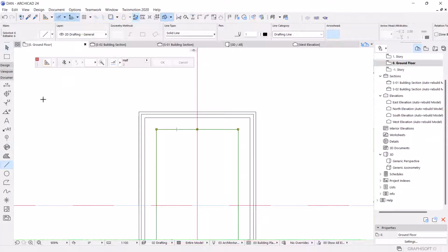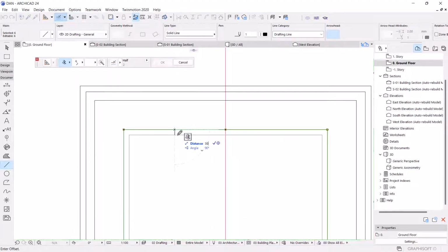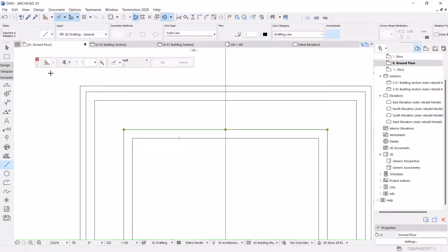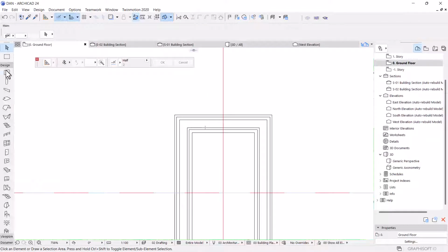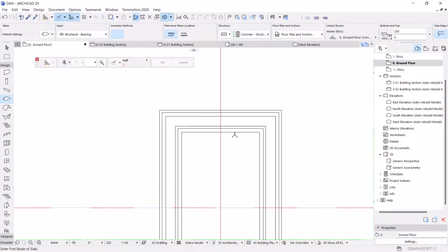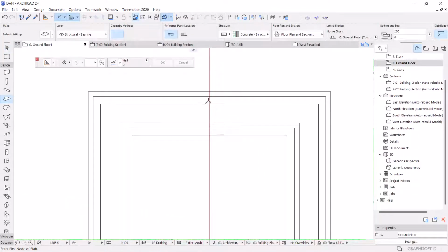Let me click the line, and this I can offset like 30 mm. Then let me offset outwards 20 mm, then enter. So we just repeat the same thing. Or if you want, you can just go and drag a copy of the same from above.